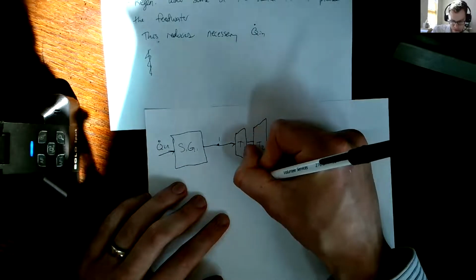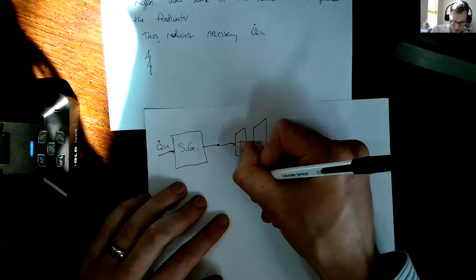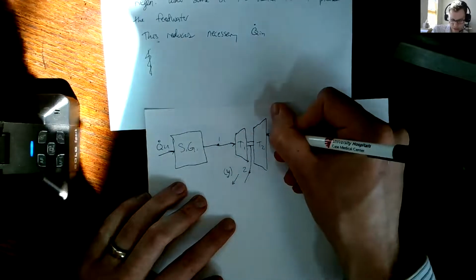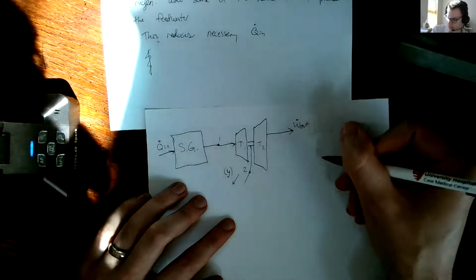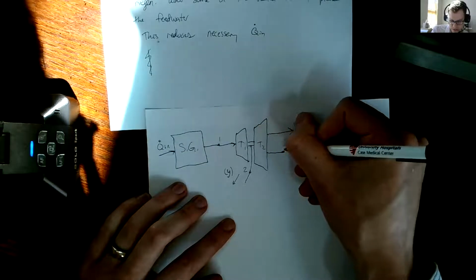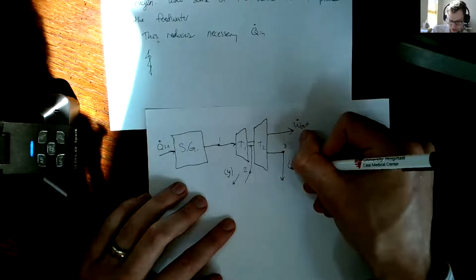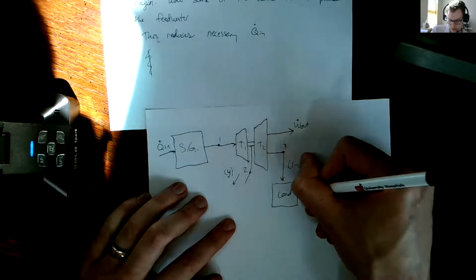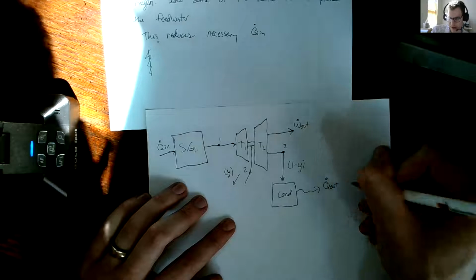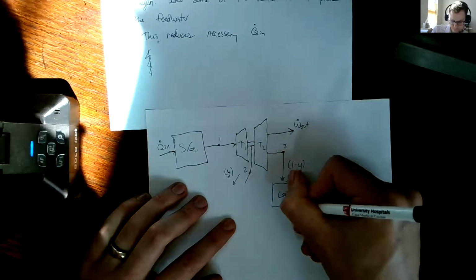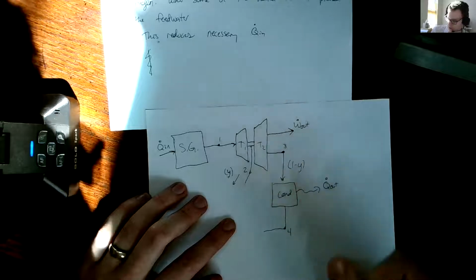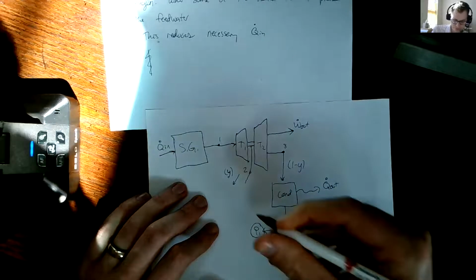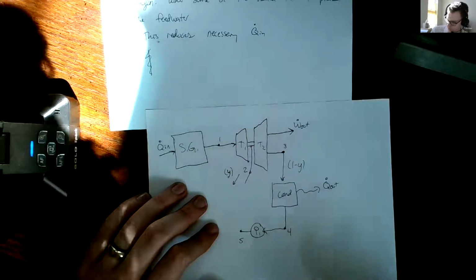We're going to have a state 2 come off here, and we're going to have a fraction of the water, Y, go this way on this path. We're going to have power coming out of both stages of the turbine. We're going to come out here to state 3 and divert the rest of it, which is 1 minus Y, into a condenser, which is going to pass waste heat out to the environment. This is going to get to state 4. We're going to run this into a pump, our first pump, which is going to pump it up to state 5, pressure 5.